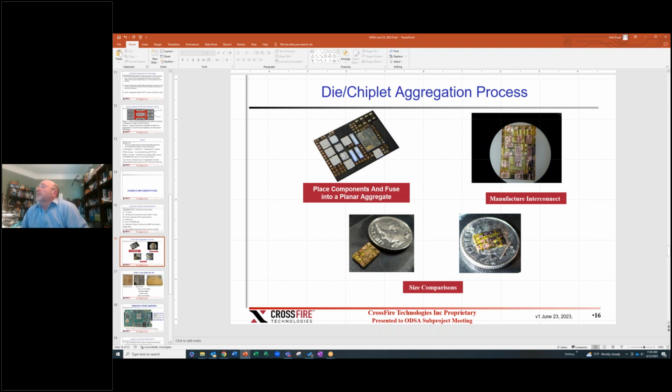So here, what we're doing is we're just reconstructing a die out of aggregated chiplets or dilets. And I'll use dilet as a term, as an unpackaged die that's meant to be packaged, to separate it from a chiplet. It just has a different use case. So in this case, this is something that we can do right now and support whatever IO densities.